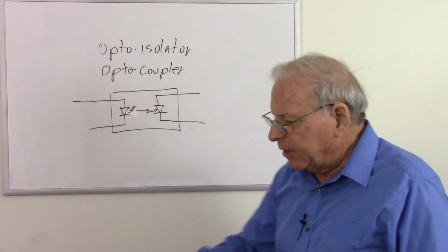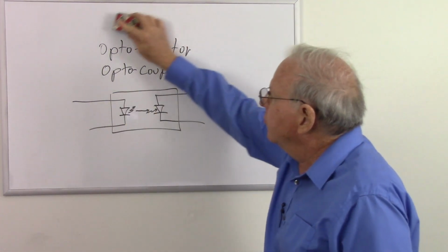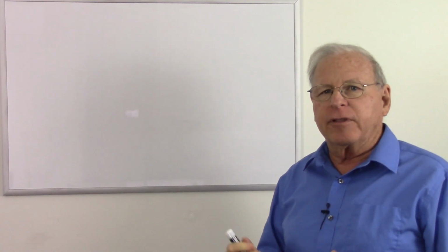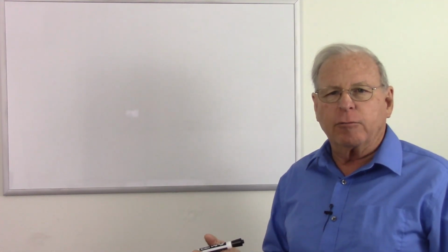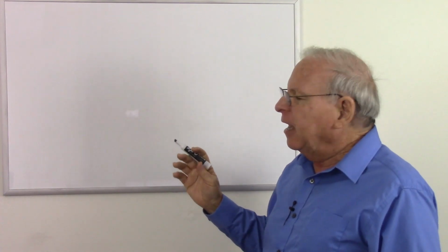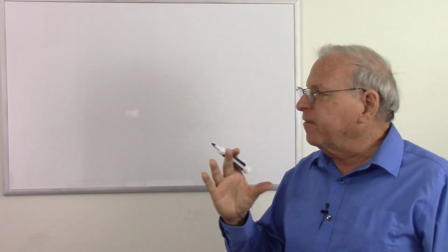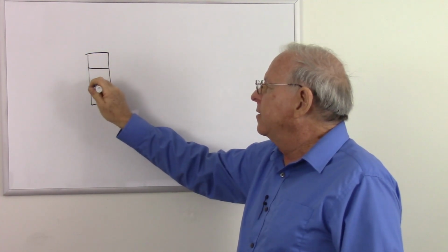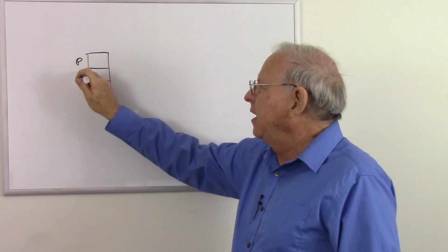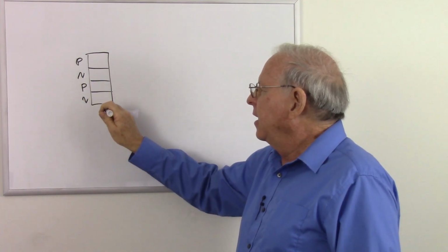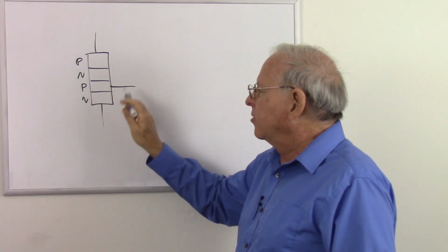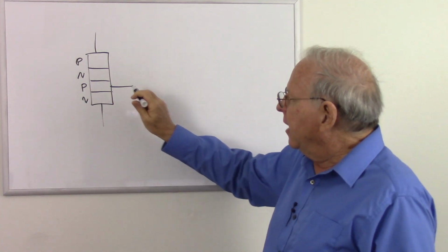The next common type of diode to talk about is the silicon-controlled or silicon control rectifier, depending on who's talking. Also sometimes called a thyristor, named after the thyratron tube, which is a vacuum tube that acts similarly. The SCR, or silicon control rectifier, is a 4-layer device. So instead of one p-n junction, we have 3. So it's something like p-n, p-n, and we have a connection here and a connection here, and one of these, I don't remember off the top of my head which, I'll just put it to that one, has a third connection called the gate.